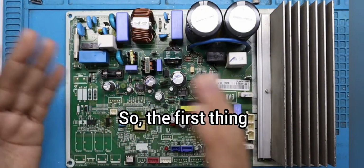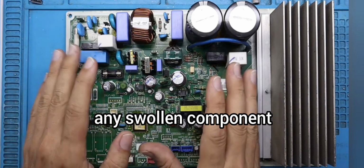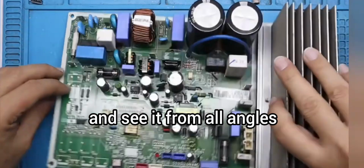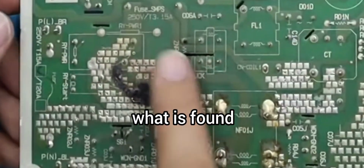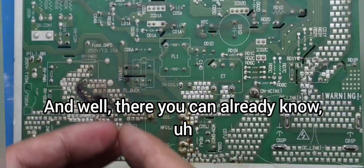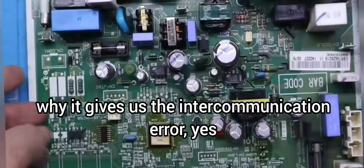So the first thing that we have to do is see if there is any melted component, any swollen component. Turn the board to several places and see it from all angles to see what can be found. On this board, what is found is that there is a spark mark. Look for yourselves how it burned that area. And well, there you can already know easily where the error is, let's say. Why it gives us the intercommunication error?